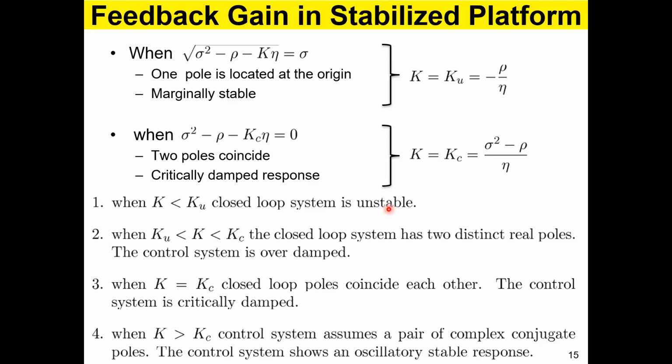It goes to unstable area because when you reduce K, it goes from whatever positive value to 0 and then to the negative side. So when gain is negative, it is not actually negative feedback, it does positive feedback, right? So it doesn't serve the purpose.